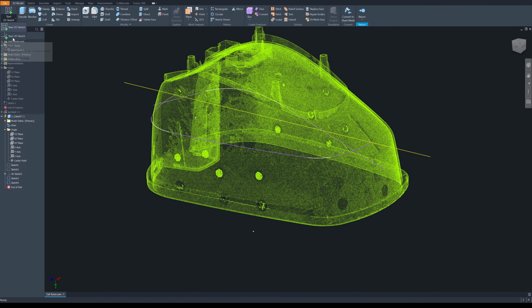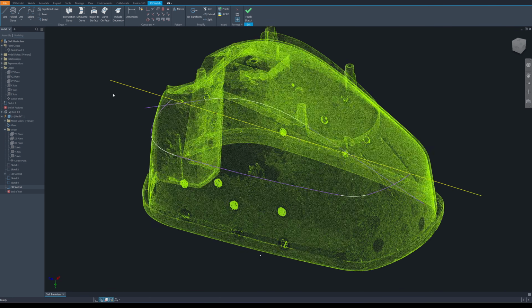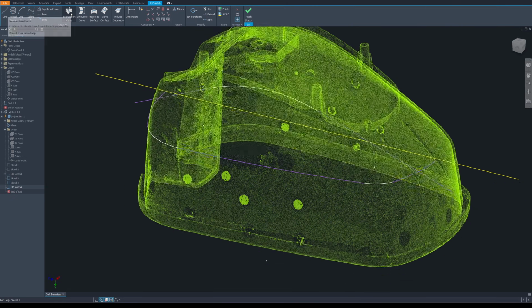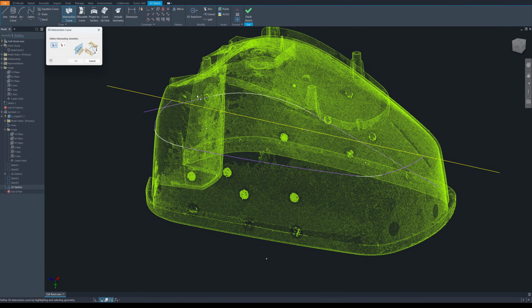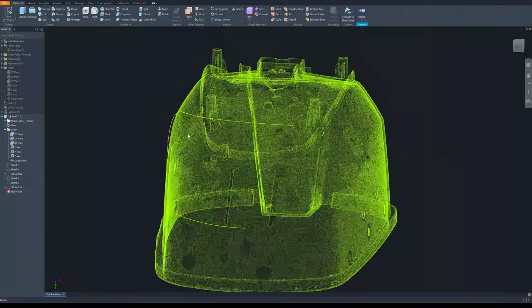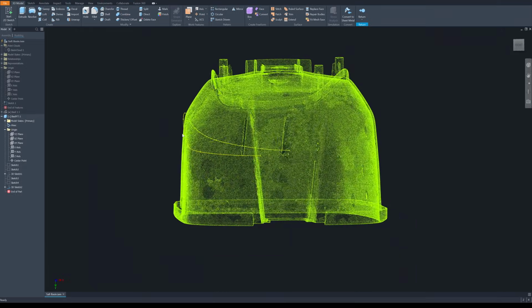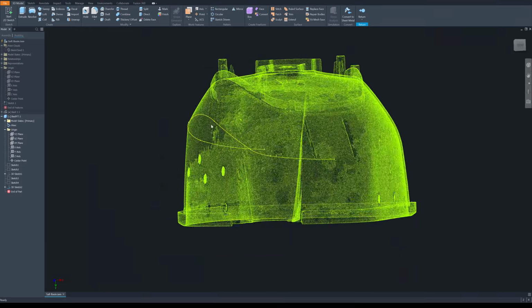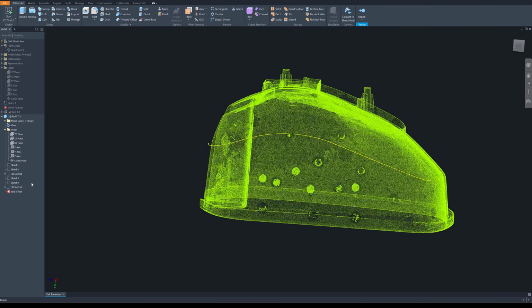Another 3D sketch here, and I'm going to create an intersection curve by using these two sketches. This will be sketch 1 and this will be sketch 2. Click on OK. Okay, now it's getting close enough because I need to leave some space for the fillet.